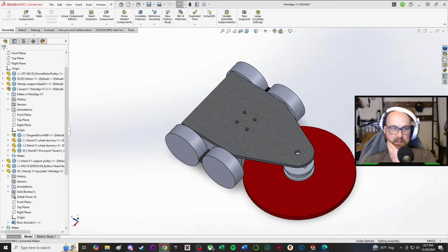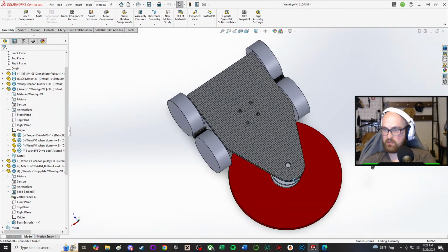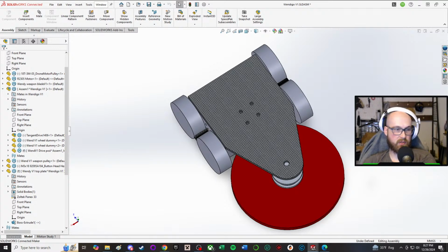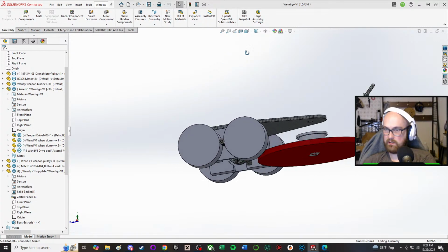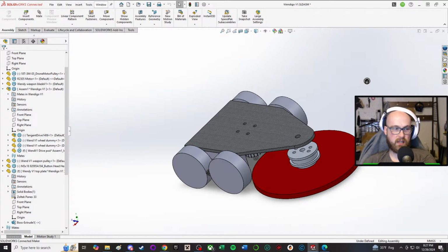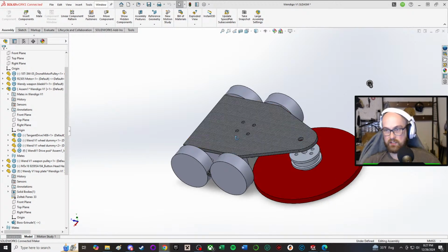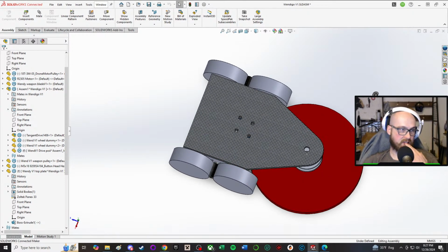But yeah, the idea is that I just wanted a robot that could drive forward and backward and still hit the opponent. Originally it was going to be a vertical, but I realized vertical spinners want forks in the front. And if I have forks in the front, I can't really have forks in the back. That just wouldn't really work out. So I decided on a horizontal, and I decided that an undercutter would be the best choice. The reason is I felt like it's supposed to be more of a control-y bot, which I thought an undercutter made more sense for.